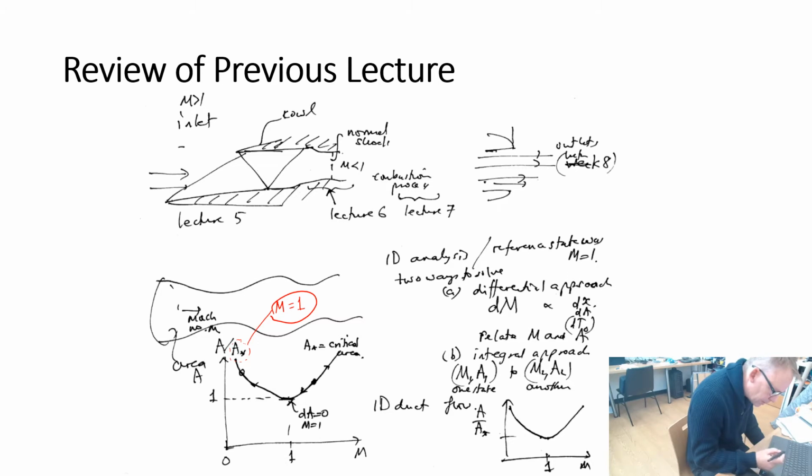Two approaches that we discussed in the last lecture for trying to analyse this class of problems in duct flows. Basically a differential approach of trying to relate the change in Mach number to a change in either distance, change in area, or change in the stagnation temperature, or an integral approach, which is to literally relate one state to another through a conservation principle.